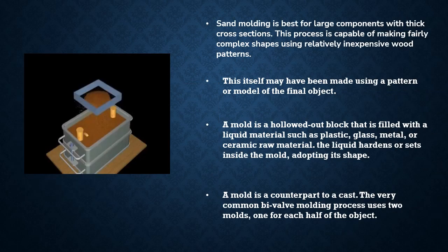This is the picture of sand molding. Sand molding is best for large components with thick sections. This process is capable of making fairly complex shapes using relatively inexpensive wood patterns. The mold itself may have been made using a pattern or model of the final product.